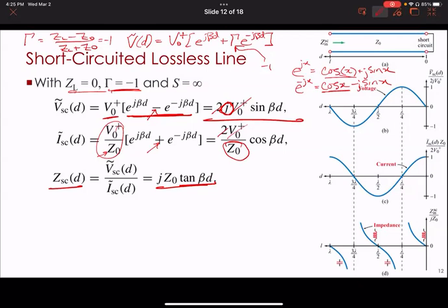Now, before taking this class, if you went into your circuits lab and you just shorted something to ground and then looked at the impedance looking into it, well, the transmission line had no effect. So you saw whatever the thing was at the load, you saw a short circuit. If you hooked up your multimeter and tried to figure out what the resistance was, it would just say 0 because you've connected a short circuit to it, but not here. Here, it's given by this, okay?